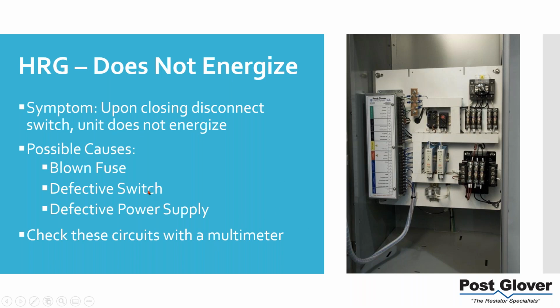Once again, defective switch, that happens rarely, but it's possible. Defective power supply, it's also possible. Fuses, I would say, the most common thing. Look for that adapter switch as well. Just something to think about. If that terminal strip is loose, make sure it's pushed in. Otherwise, it's possible you have a bad controller. There's a few things. These are probably more common, but you can check those circuits with a multimeter.